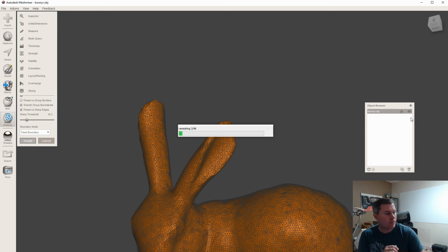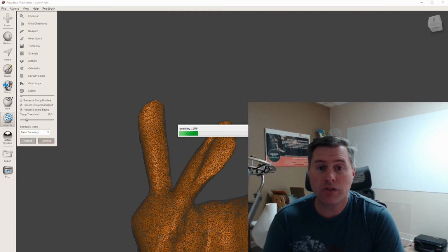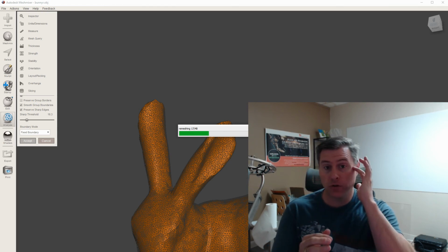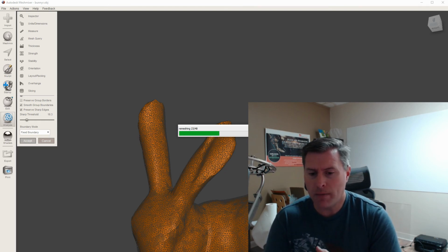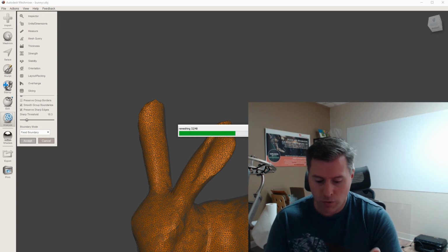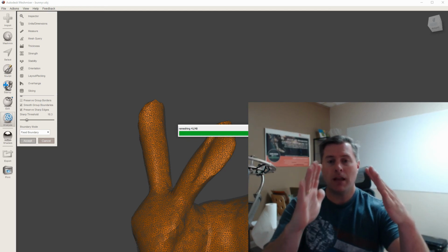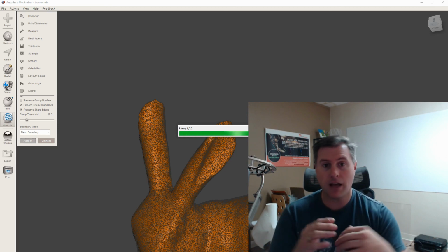Right, so that's some, let me make myself bigger so you can see me over here. Hopefully this is working. So that hopefully shows you some more advanced tools, but really it's that fit primitive that helps you get some sort of starter geometry in there that's really useful for doing mesh cleanups that are maybe more advanced, where lots of areas of things are missing, because sometimes it happens with scanning where you have a large area that you just want to be flat, but you have things coming up and things coming up. It's very easy to flatten those out, fit primitive, and put a plane in there, and then mesh that in.